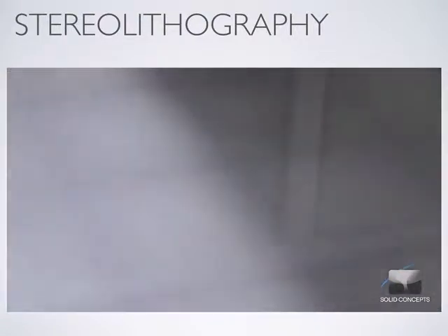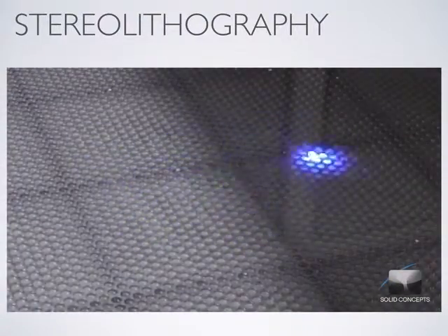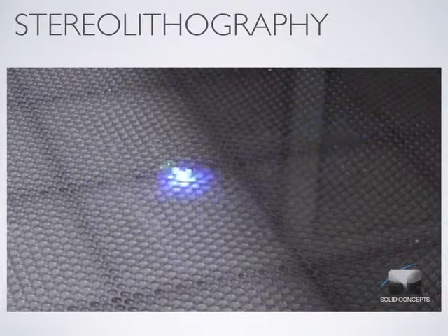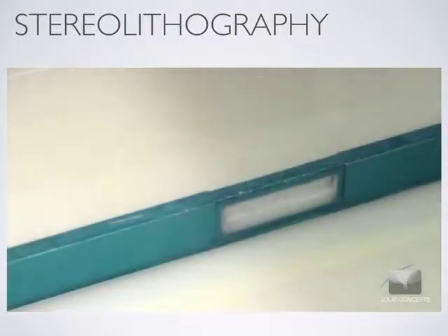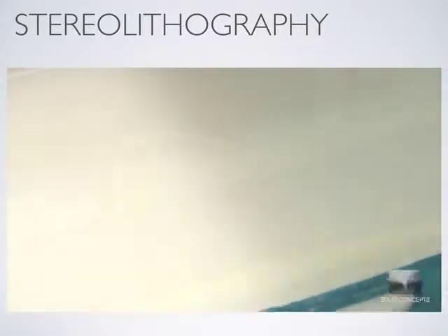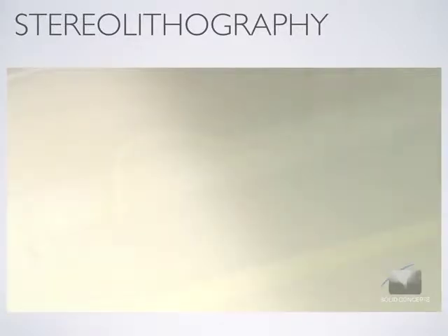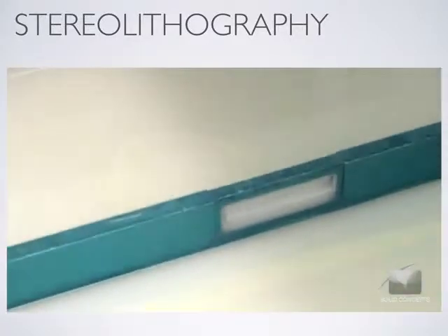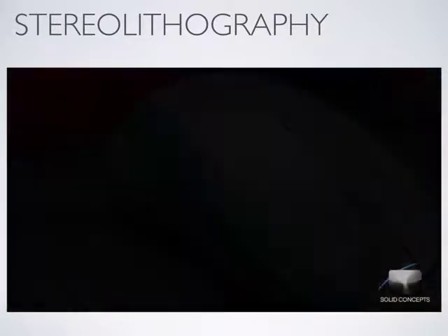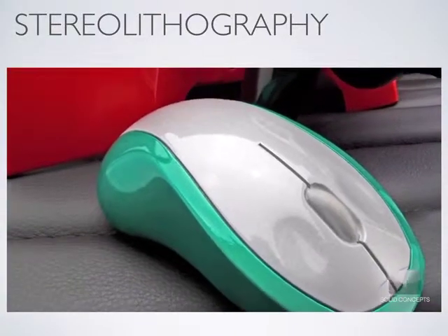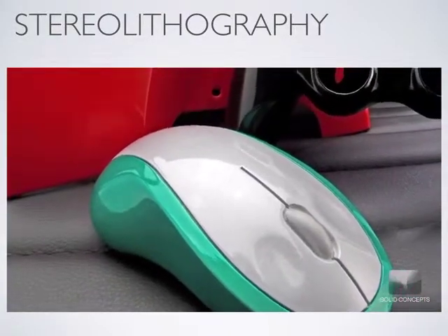Stereolithography is a rapid prototyping process used to create parts from 3D CAD data in a matter of hours. SLA is a highly accurate additive manufacturing process and may also be referred to as rapid prototyping or 3D printing. Models created with this technology are typically used as concept models for form and fit studies or as master patterns